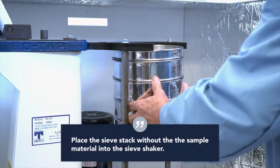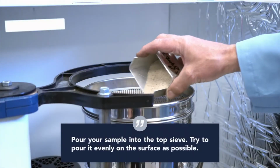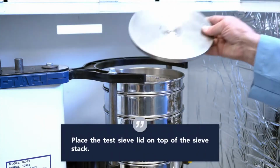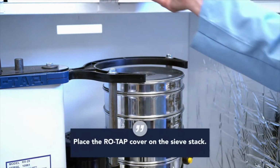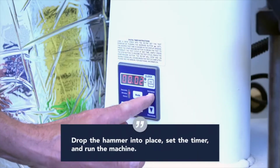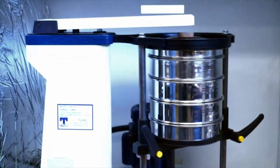Place your sieve stack without the sample material in your sieve shaker. Pour your sample into the top sieve. Try and pour your sample as evenly around the surface of the top sieve as possible. Once your sample has been poured in its entirety, place the test sieve lid on the top. Place the Rotap cover with the cork plug on top of your sieve stack. Drop the hammer into place. Now, set your timer and turn your machine on. Once the sieve shaker has finished its cycle, it will turn itself off.